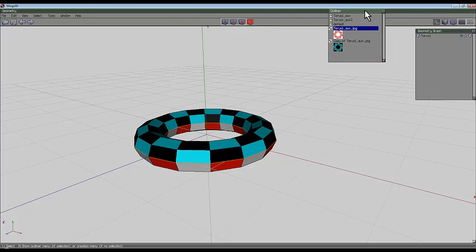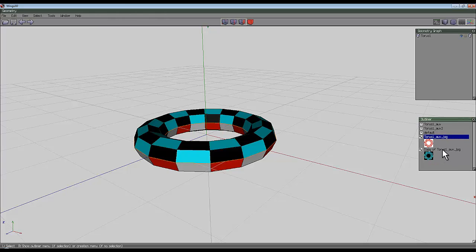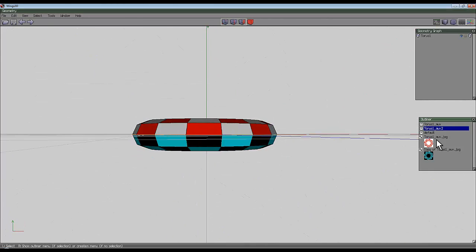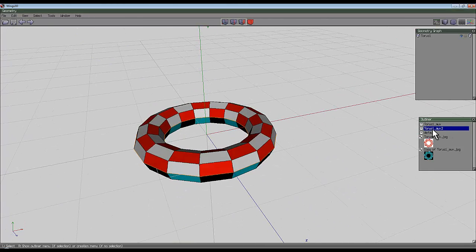So there is another way of doing that. It's worth knowing, I discovered. So if you right click on this and you pick up the image, then you can left click on the object to select it, the material, select it, and then drop picked up object and select diffuse. And so do this again, pick up the other image, select that, right click, and then drop pick up to object, select diffuse, and you can swap them around that way. So that's the alternative to just dragging and dropping the textures over the materials.